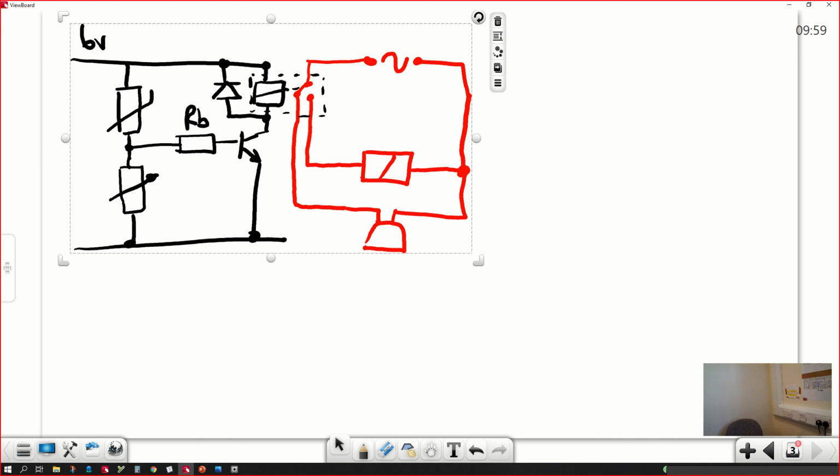The relay coil can only be one of two states. Okay? So that means that at all points, one of these two devices is going to be on. So rather than the circuit having an output or having zero output, like the motor, this is always going to have an output. The only difference is the output changes over between two things. You get them the right way. The relay is shown in its rest state. That switch is showing as if the relay is off.